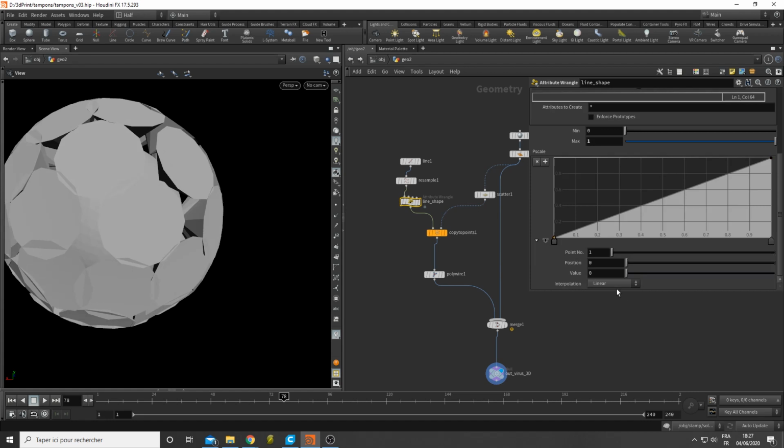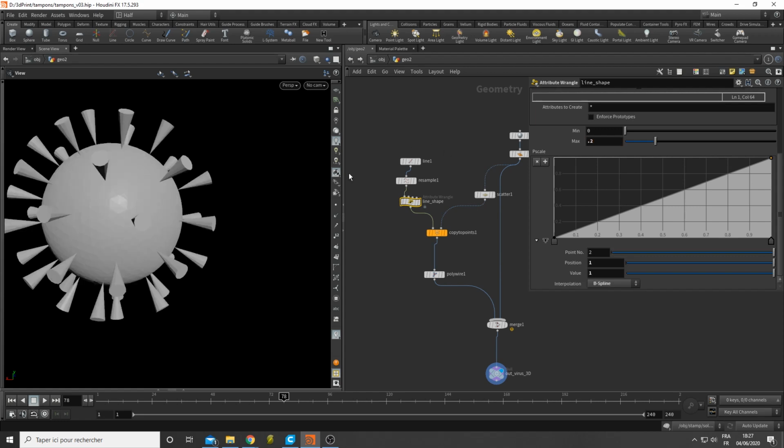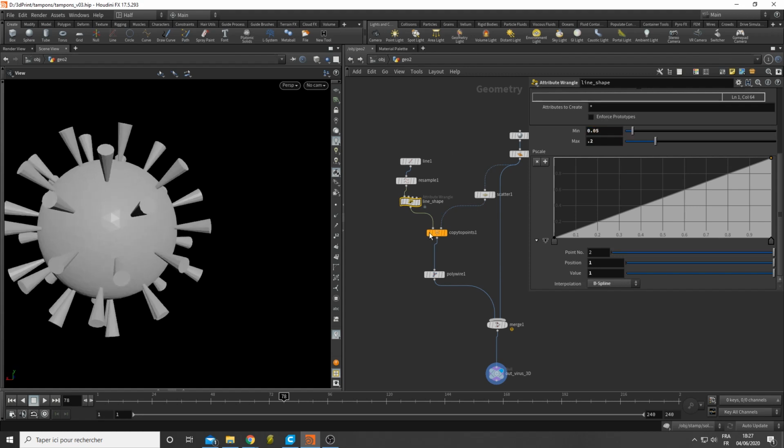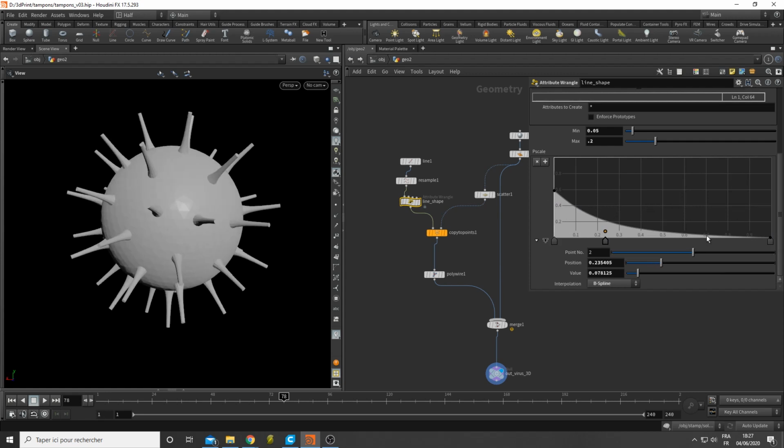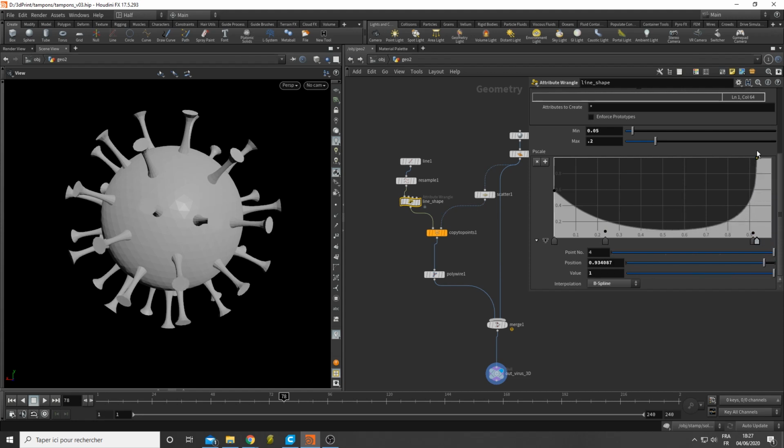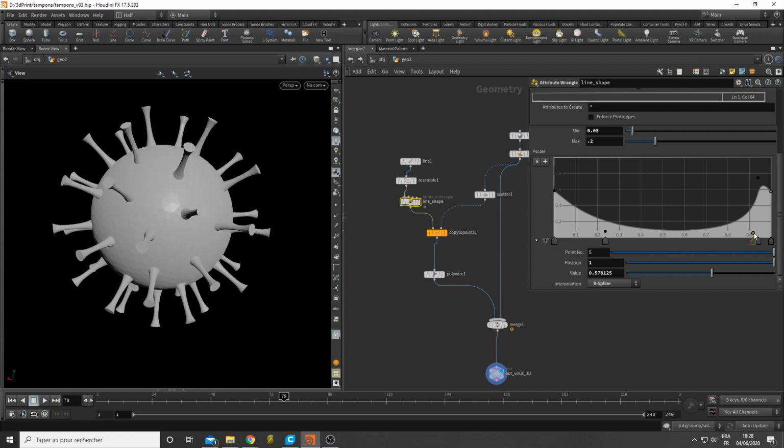And let's go back into the line shape and start working on this profile. I like to use B-spline for a more natural look, and it's going to go maximum to 1.2, I'll say, and minimum 0.05. Yeah, that's good. Let's start with the base. The base is going to be a bit wider, so I'm getting thinner, plug this up to the very tip, and then here it's going to flare, and then it's going to smooth back down.